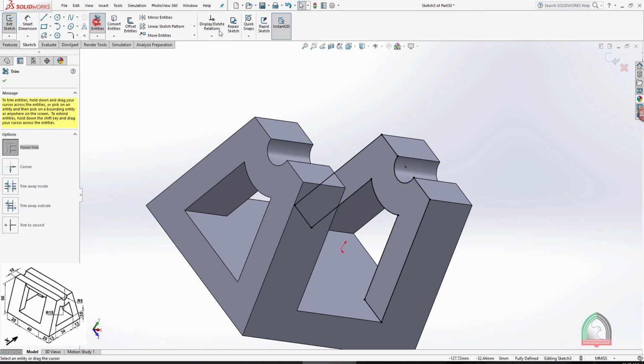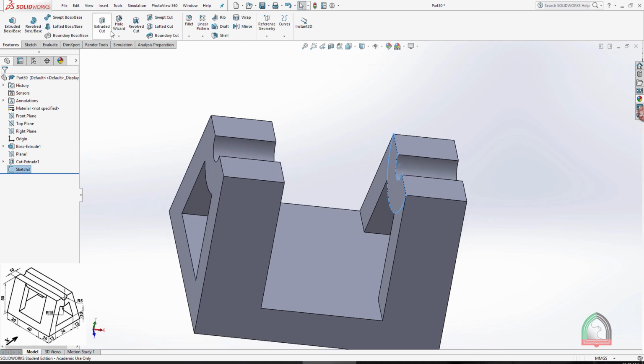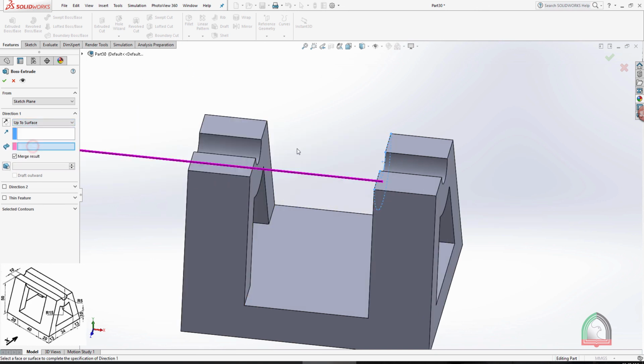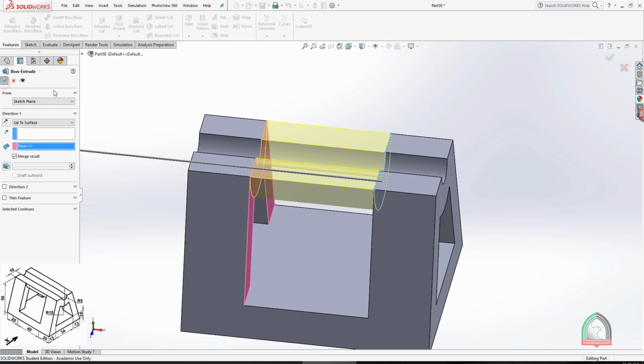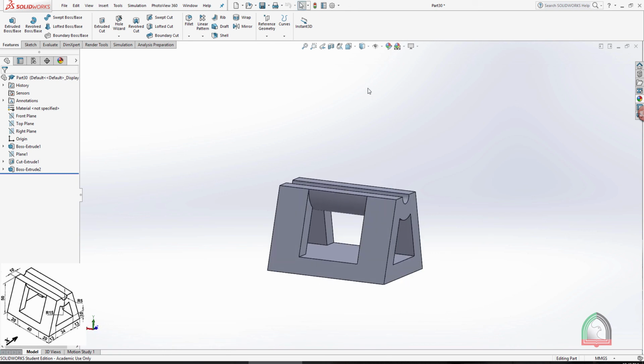What I want to do is I need to remove the unwanted portion. I don't need this one, and I want to extend this one. Here also we can cut away, and I'm extending this by using this. I can extend, exit the sketch. Now go for extrude till up to surface, this surface. So this is the final result, and here we can check for different views.